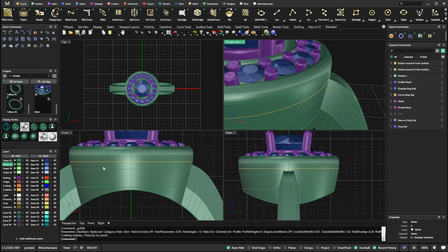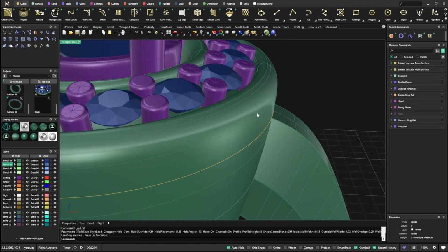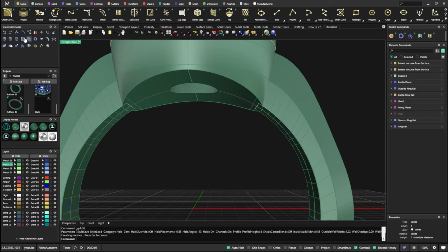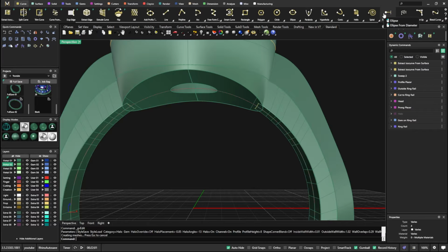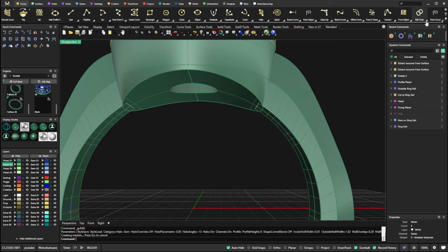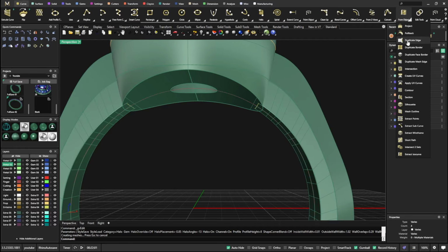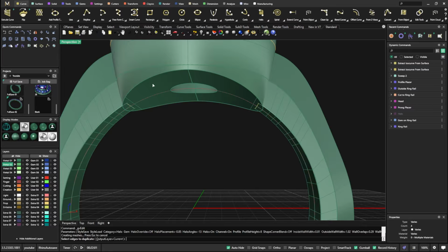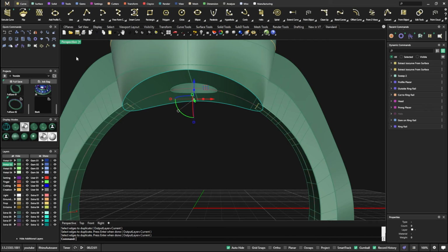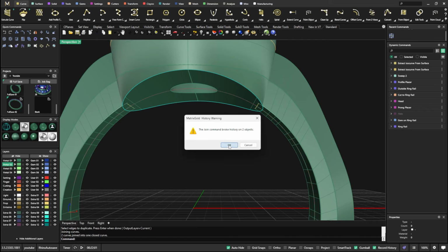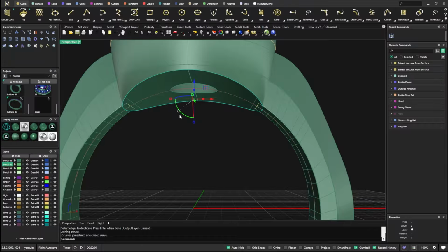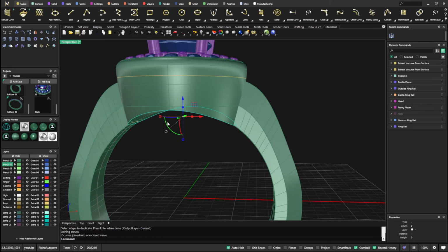All right, next thing we're going to do is on our halo here. I keep wanting to go to my quick command ribbons there, and they're not there because we're using 3.5. We'll scroll all the way down here, and actually from object, we have our dupe edge. I'm just going to take that and bring it over here, and I'm going to drop it right in there and select it. And I'm going to take this, and then right click, and then while they're still highlighted, go ahead and join those together. It broke history, but that's okay. We don't really need it for the most part.